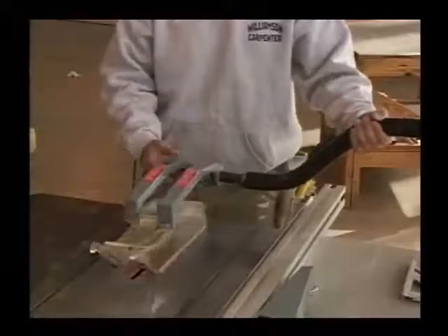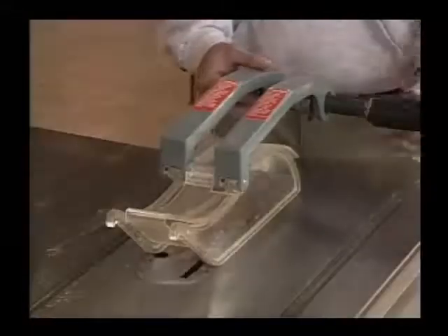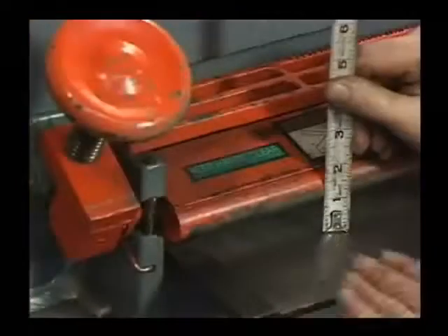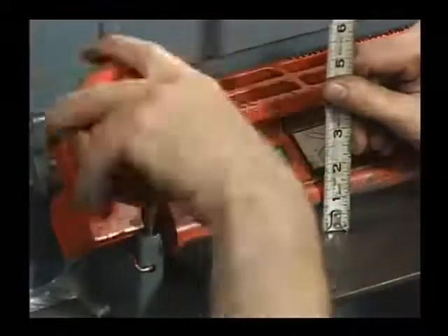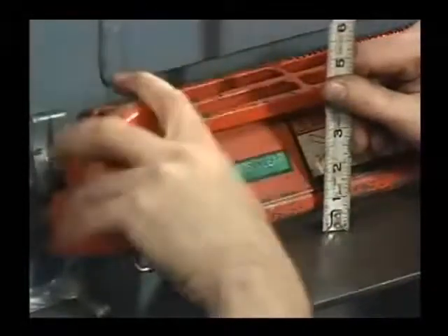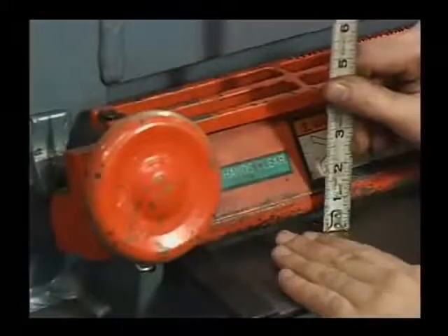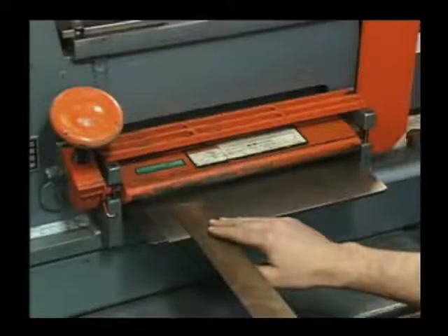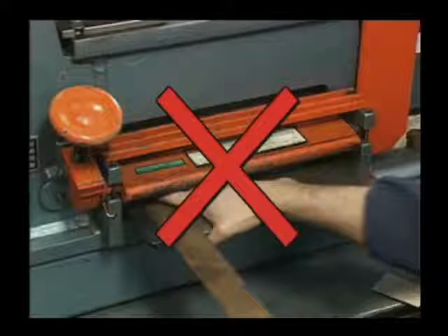Because of the way that they work, these types of guards must be inspected before each use as well as every time there is a change in the machine setup. It is particularly important to make sure that the guards are properly adjusted in order to allow materials of various sizes to pass through without sticking or kicking back. Additionally, adjustable and self-adjusting guards must never have gaps or openings large enough for any body part to slip past.